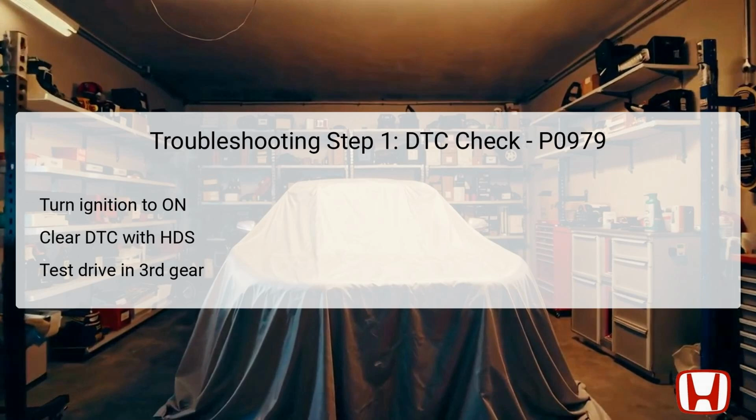Following this procedure, test drive the vehicle in third gear for at least 1 second. The purpose of this specific behavior is to allow the system to recalibrate and potentially recreate the fault under controlled conditions. After the test drive, use the HDS to check for any pending or confirmed DTCs. If DTC P0979 is indicated, the failure is duplicated, and you should proceed to the next troubleshooting step.